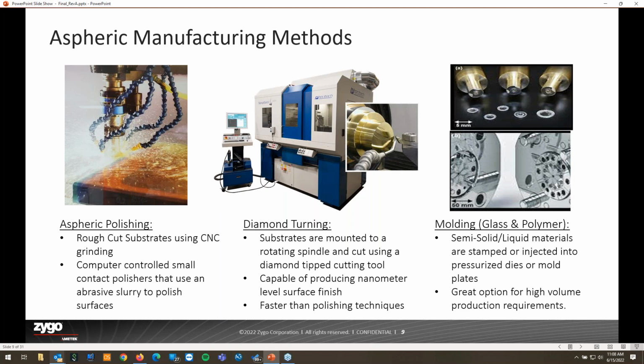So there's a lot of metrology involved, where you're taking it to a polisher, measuring the deformation, taking it back to a polisher. And so a very high level of form error can be acquired because of some of the finishing techniques that are involved with polishing. So MRF and IBF allow you to reach optics that have a very tight and controlled surface wavefront spec, and also a surface roughness that is fairly smooth.